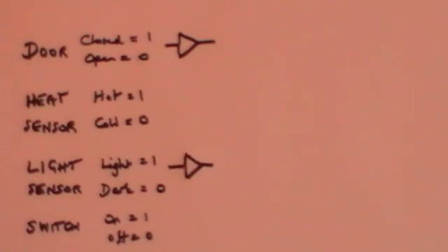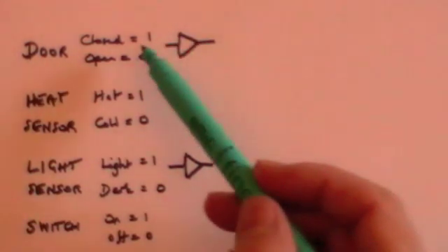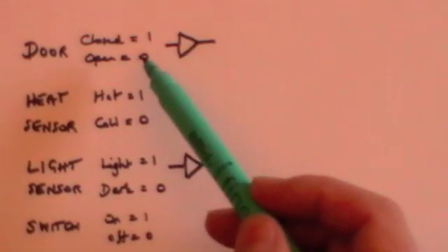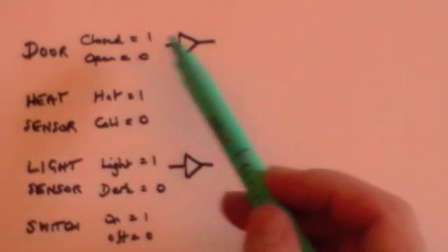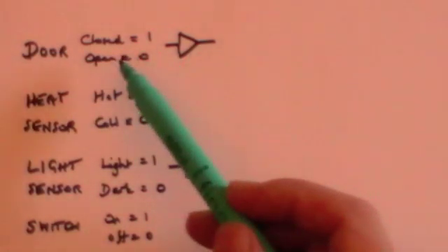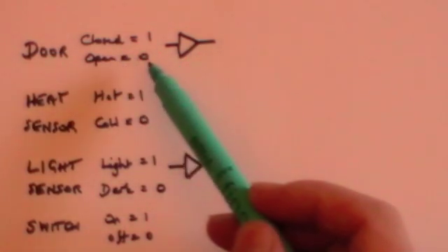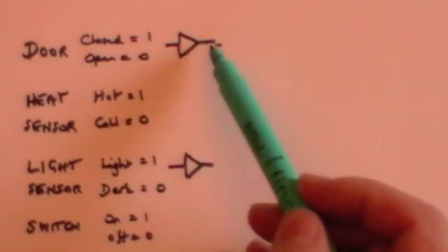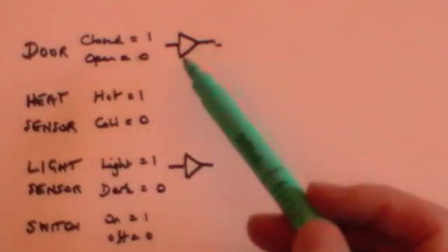Well, firstly, I obviously want to have a positive voltage if the things that I'm worried about happen. At the moment, I'm getting a positive voltage if the door is closed, but I don't care if the door is closed. I want to know if it's open. So I'm going to put a NOT gate here, because then if the door is closed, I will get no voltage out of the NOT gate. But if the door is open, which of course ordinarily means there's no voltage, I want the opposite. So I want a positive voltage coming out when the door is open, because that's what I'm worried about.